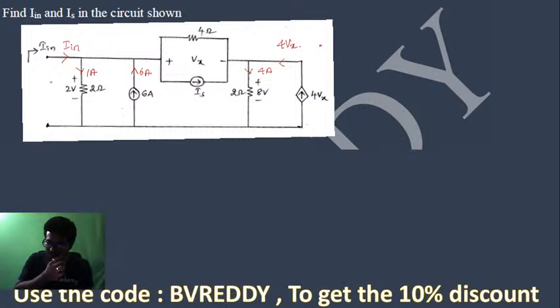Now tell me this thing here. This is IN. IN I want to get now here. So here this is 1 ampere is going, this is 6 is coming. Here this is 1 ampere, means this current must be 5 amperes. This current is 5 amperes. Right. The entry current is 5. Now here this current must also be 5 amperes.